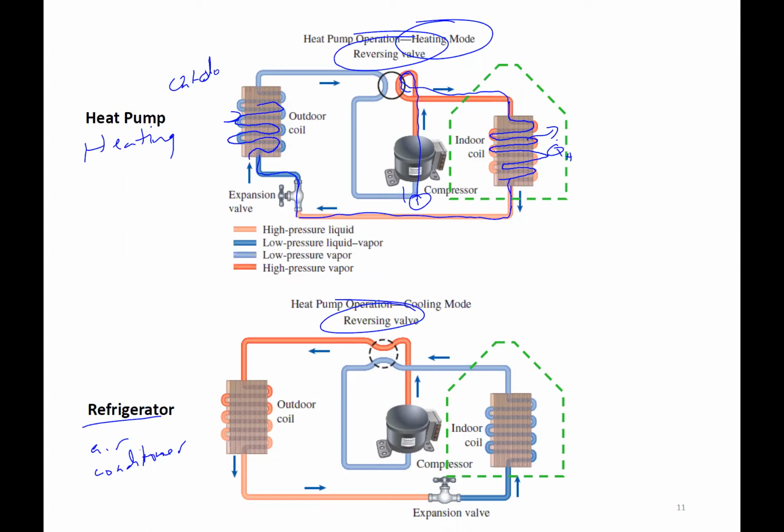This is the outdoors here, right? So now we can pull heat from the cold outdoors. The refrigerant has to be at a lower temperature than the outdoors. So if it's 0 degrees Celsius outside, that refrigerant needs to be at negative 20 degrees Celsius. And then you can see how, being at negative 20, it might start icing up that heat exchanger.